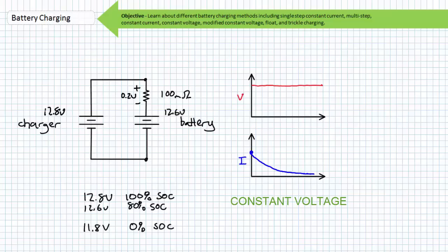If we were to plot current over time for a constant voltage charge, we would expect high initial current that progressively diminishes. At the end of the charge cycle, the battery begins to saturate and current drops. Lead-acid batteries require periodic full saturation to prevent sulfation, where sulfation is the buildup of lead sulfate crystals that robs electrodes of functional surface area. Full charge occurs when current drops to a set minimum level.